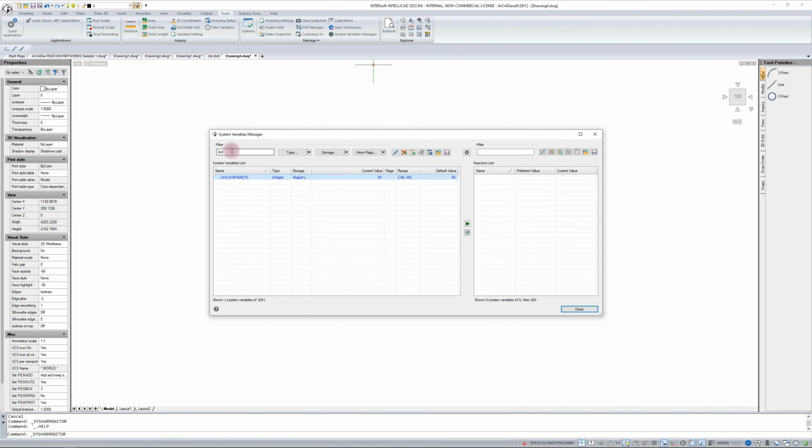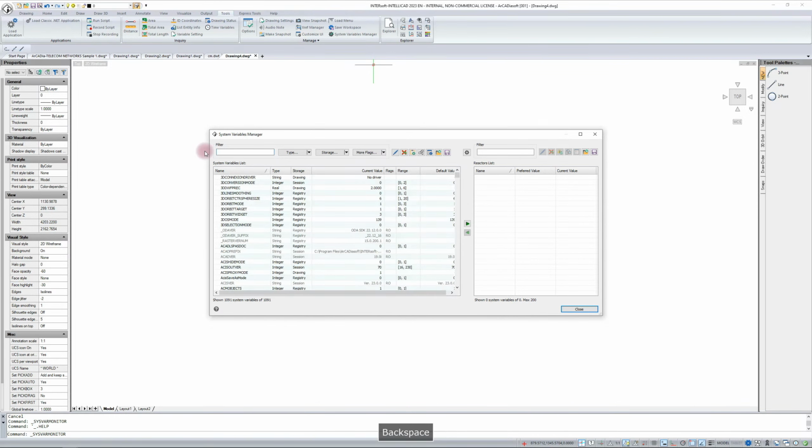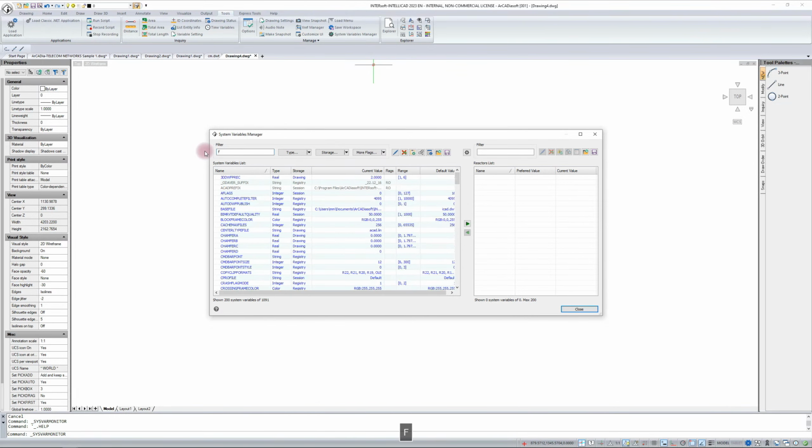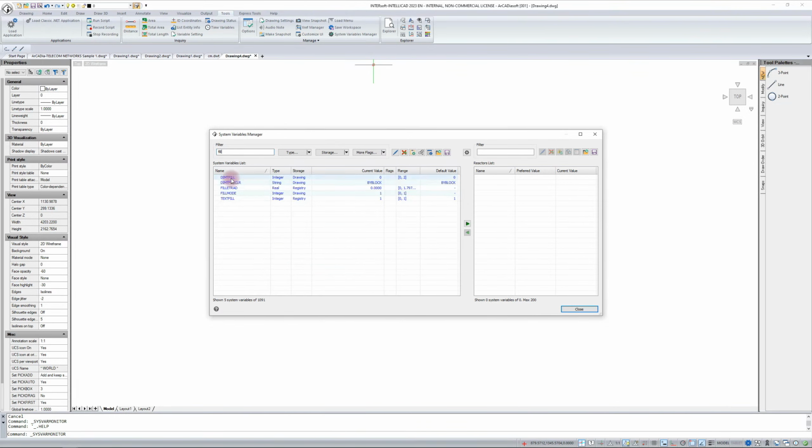If we do not want this inactive layer to be displayed, we can change this value from 50, for example, to 90 or 1. Whatever we want, so that this view or drawing is intuitive for us and not for the program. Such a variable as fill mode is a variable stored in the drawing, just like the first one I mentioned.